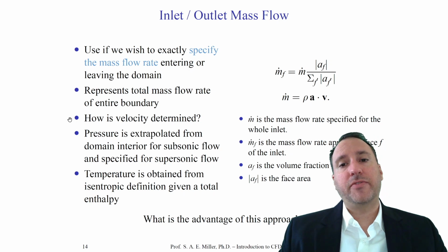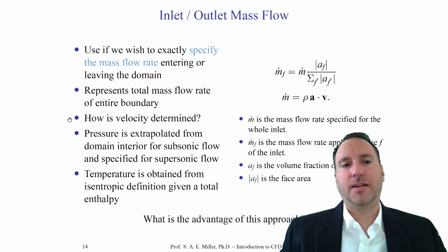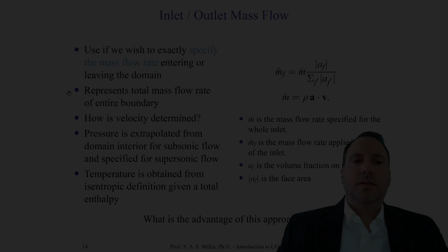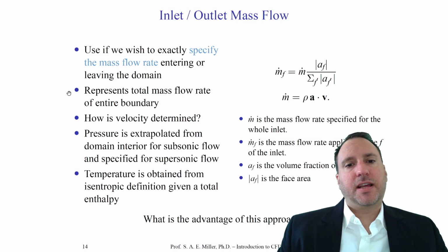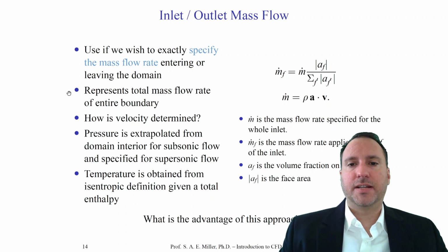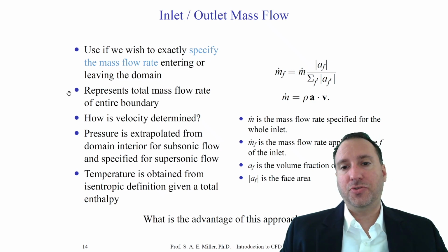And that way you'll have increasing density or decreasing density overall, averaged in your computational domain. So if you have an incompressible solver, make sure that mass flow rates at the inlet and exit are indeed equal. So the wonderful thing about this, especially in the chemical engineering or petroleum industry, is we get to explicitly state and set the mass flow rates. It is unacceptable, for example, in the petroleum industry to lose track of oil quantities.